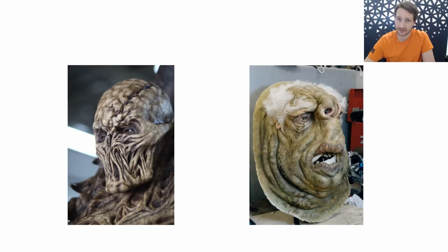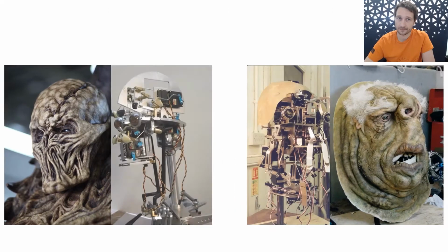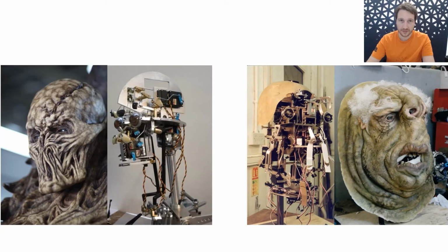These latex faces appear very real and very complicated, but they are just a cover. Once you tear them away, you can see their true nature. Under the cover, we have a mechanism. An animatronic mechanism has two types of elements, followers and drivers. Drivers are essentially motors, which are attached by tie rods to followers. Followers make up the moving features of the animatronic.